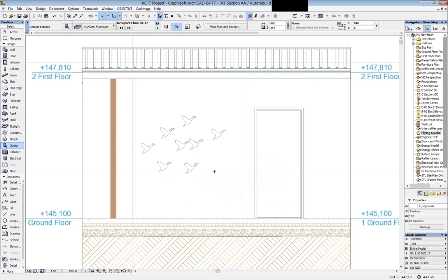Dragging and dragging multiple, obviously we can do that. Mirror and mirroring a copy for everything except doors and windows. Multiply, of course, for everything. And interestingly, rotate and rotate a copy only for morph, shell, and curtain wall. So I'm not sure why that wasn't put into ArchiCAD 17. Must have been some very tricky coding required.